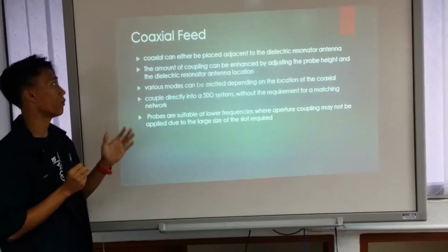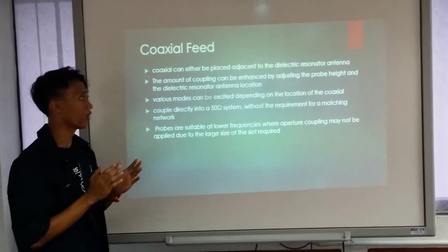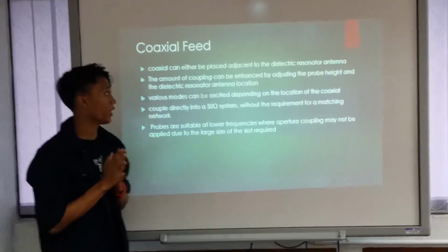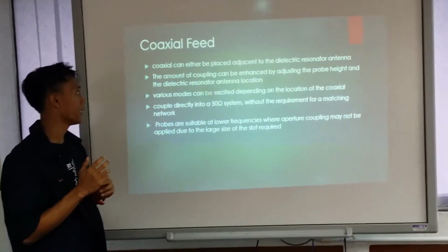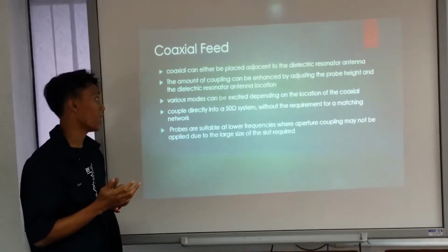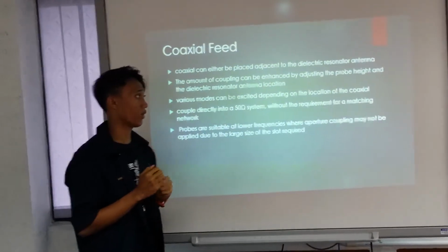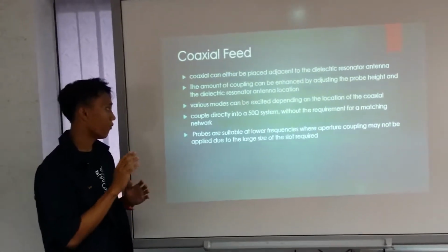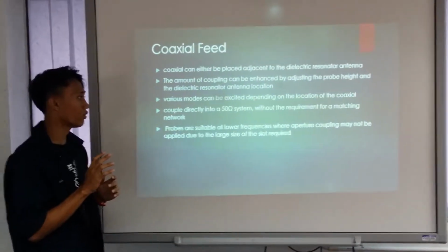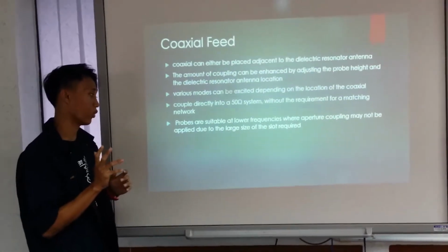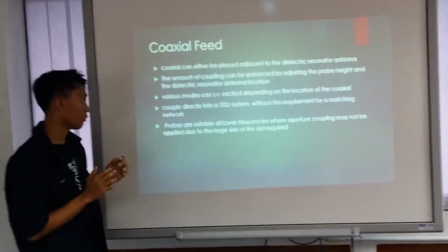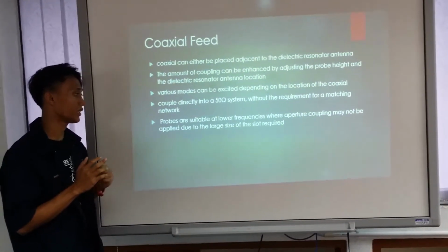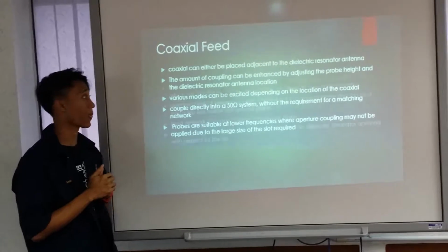the coaxial probe can be placed adjacent to the dielectric resonator antenna. The amount of coupling can be enhanced by adjusting the probe height and the dielectric resonator antenna location. Various modes can be excited depending on the location of the coaxial probe, and it is coupled directly into a 50 ohm system without the requirement for a matching network. Probes are suitable at lower frequencies where aperture coupling may not be applied due to the large size of the slot required.